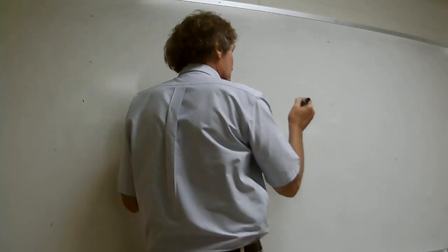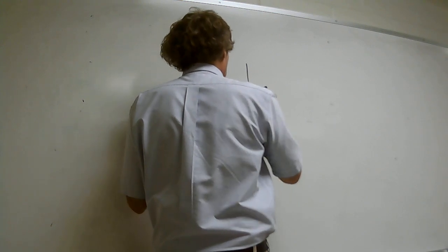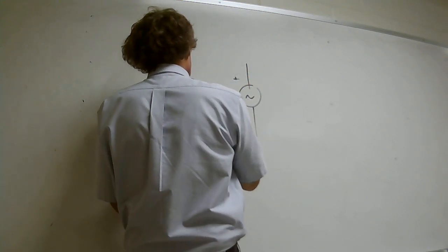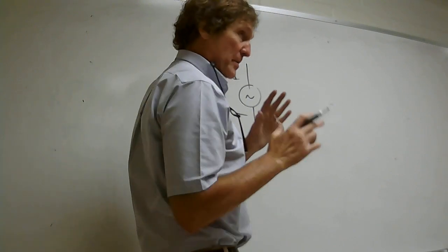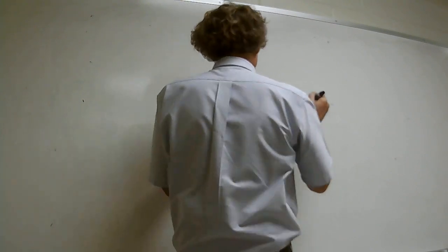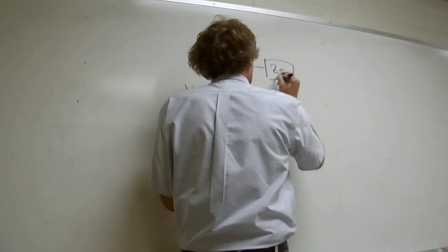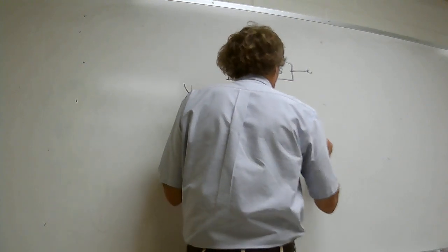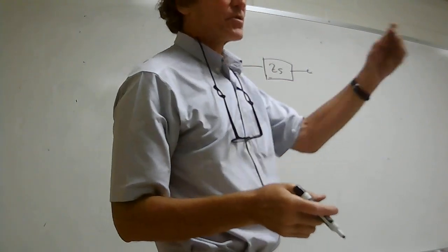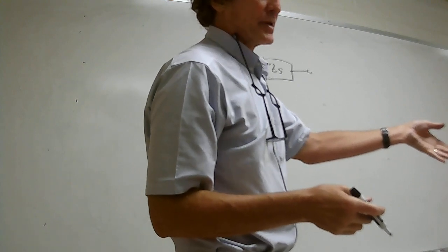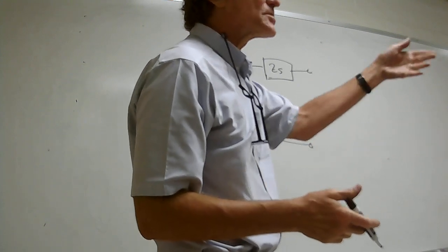So now this is a complete circuit. What do I mean by that? I'll show you what I mean. So, start with a source voltage. You're going to have some voltage here, just Vs. It can be a magnitude and angle, but it's going to be in the phasor domain. Then you're going to have an impedance here, some Z source. This is an impedance that has to do with the source itself. Are you all familiar that all your power supplies have some internal impedance? They're never zero impedance. I mean, they're close, but there's always something there.